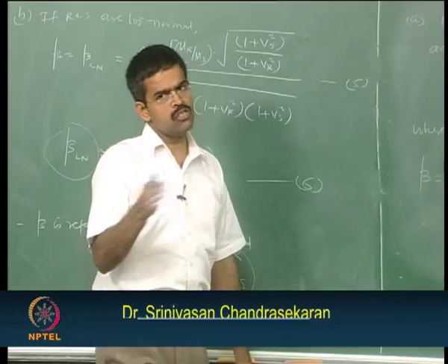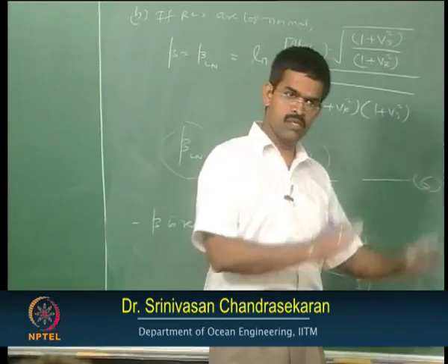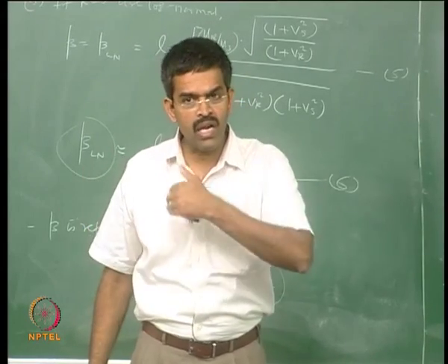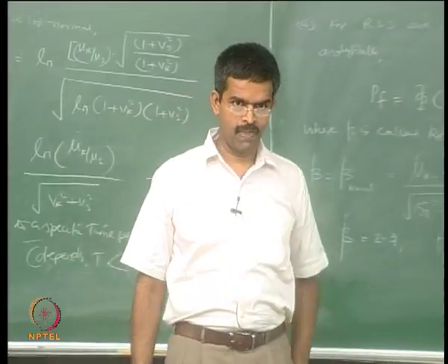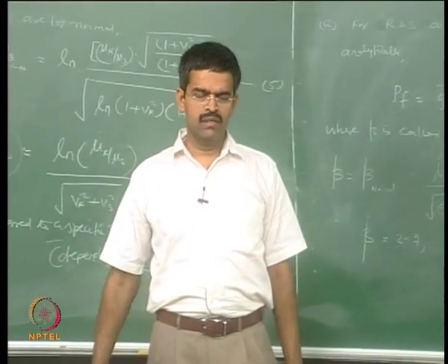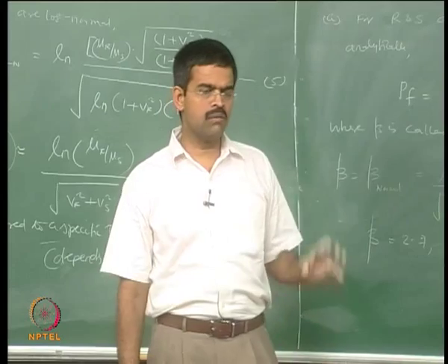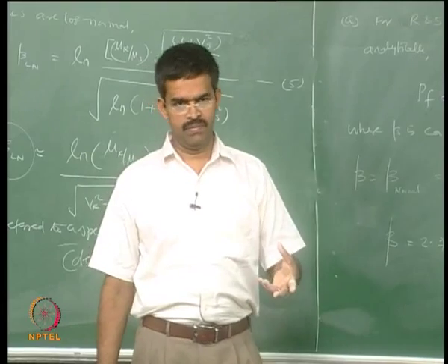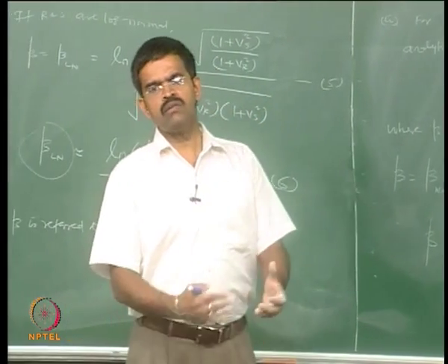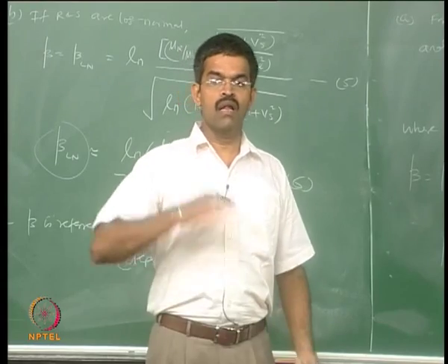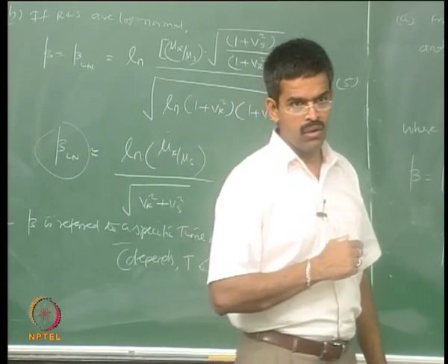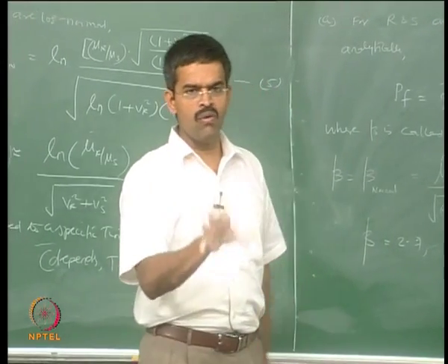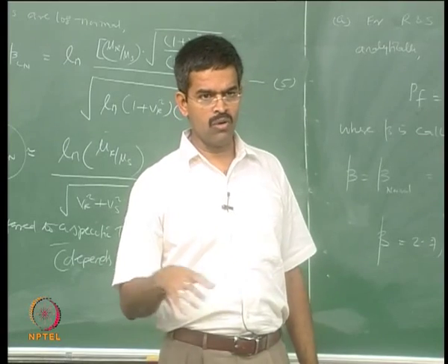Amongst these two sets of uncertainties, one is R and one is S, if we apply them onto my ultimate limit state which is governing the reliability, that is what we will see in the next lecture. So, what is the ultimate limit state and the reliability application onto the ultimate limit state implicitly, we will see in the next lecture. Then based on this, how do we classify different levels of reliability, level 1, 2, 3 and 4, how are they classified and what are the equations available for different levels. Very briefly we will look into them and we will close the lectures on module 3.